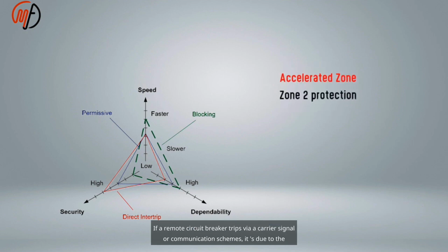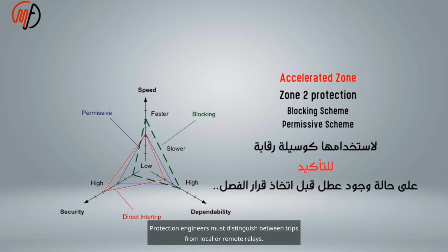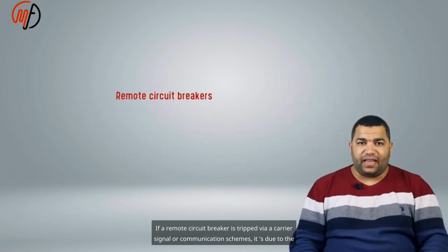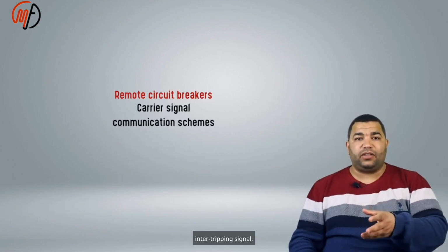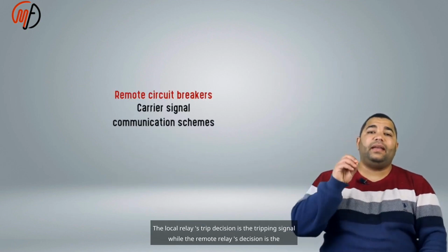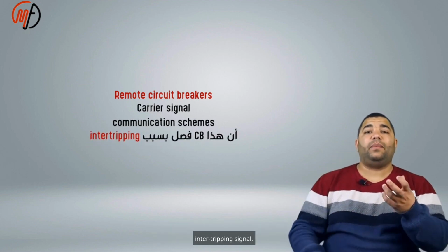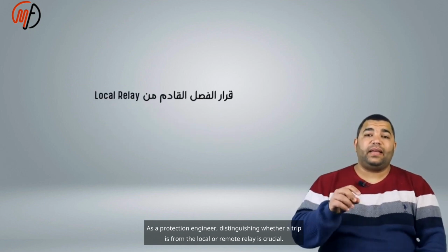If a remote circuit breaker trips via a carrier signal or communication schemes, it's due to the intertripping signal. The local relay's decision is the tripping signal, while the remote relay's decision is the intertripping signal. As a protection engineer, distinguishing whether a trip is from the local or remote relay is crucial.